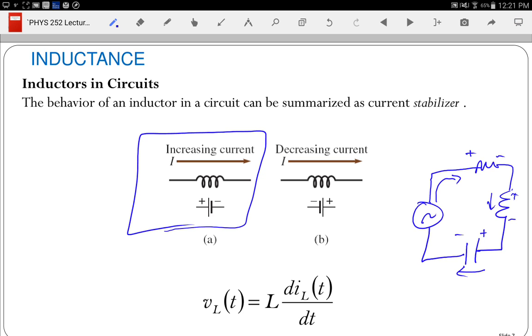But mathematically, we had the derivative of voltage. If we had a discontinuous change in voltage, that derivative would have been infinite or undefined, and so that wasn't possible. Now, if you look at this equation, using that same logic, what can we not have a discontinuous change in? Okay, so current must be continuous.